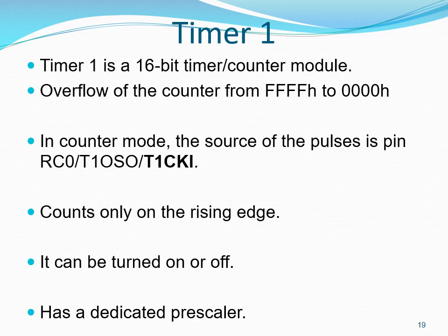Timer 1 can be turned on or off. This is unlike timer 0, which has no facility to be turned on or off. Timer 1 has a dedicated prescaler.